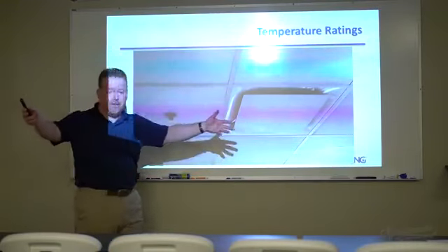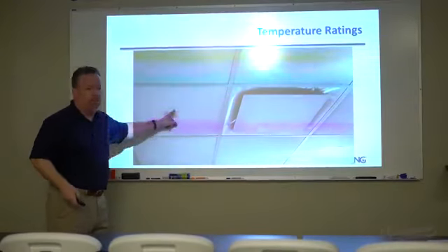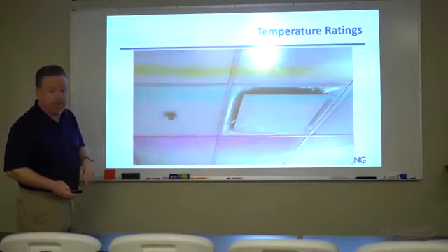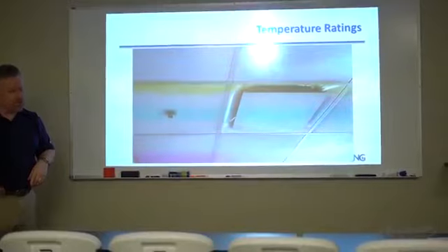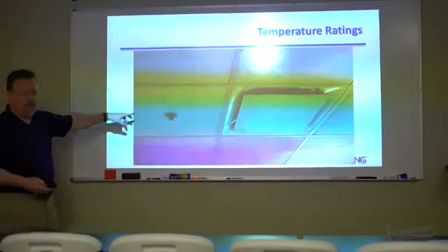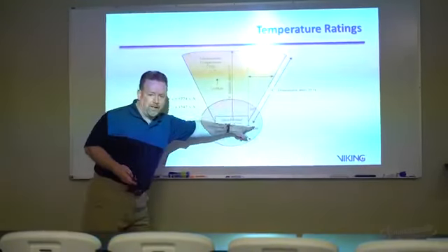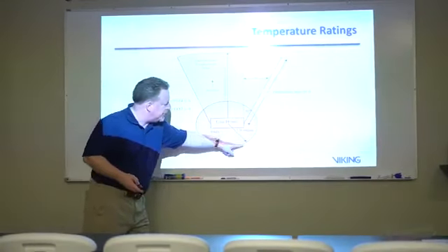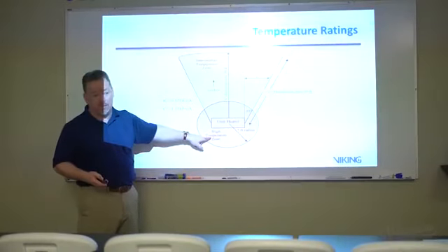So just because it's in an office environment doesn't mean that we're not going to be putting intermediate temperature sprinklers in certain spaces. So it's just the space plus the supply. Pardon? Plus the supply. Yeah, I'm saying the heating supply. Right. So in certain circumstances, like with my unit heater, the standard says that for a 7-foot radius around a unit heater, I have to have high temperature sprinklers.